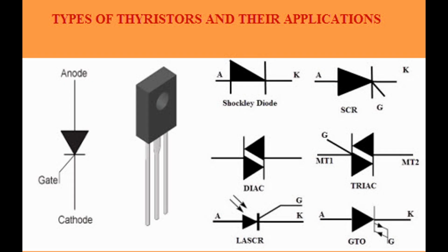Limitations. Complex gate drive requirements. Requires a specialized gate drive circuit capable of providing high current pulses for switching. Thermal management. Generates significant heat during operation, requiring effective cooling solutions. Cost. Typically more expensive than simpler thyristors like SCRs or standard GTOs due to the complexity of the device and its drive circuitry.